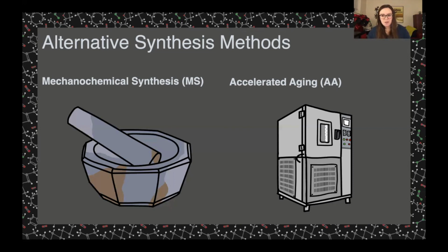Accelerated aging, on the other hand, is a very long-term process. It can take, it is measured in days, certainly, or potentially even in weeks. However, all you have to do in order to get it going, and I have here just a little converted oven that's been turned into a hydration chamber, is you turn up the heat a little bit. Depending on what time of year you're watching this or where you are in the world, maybe you could even just have it outside, like that temperature.